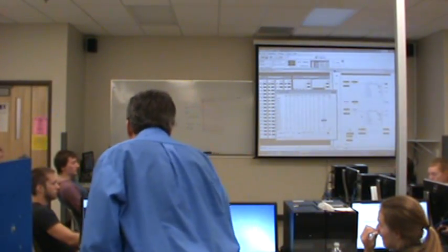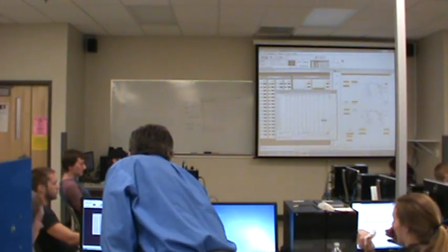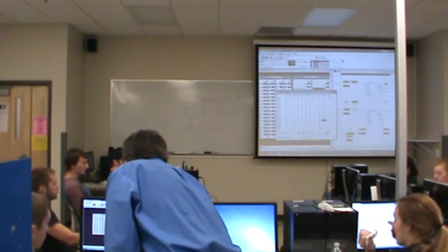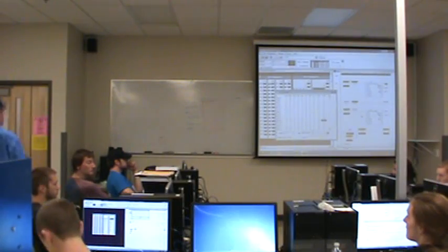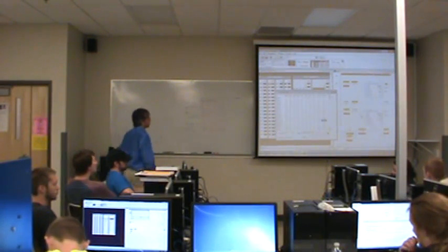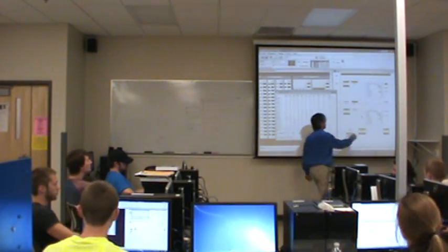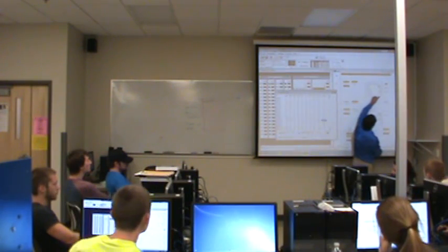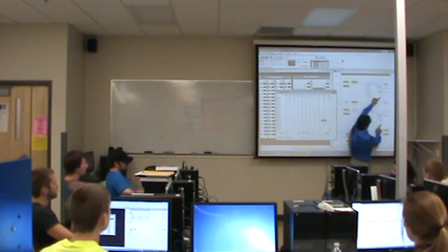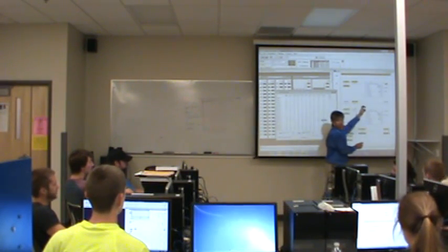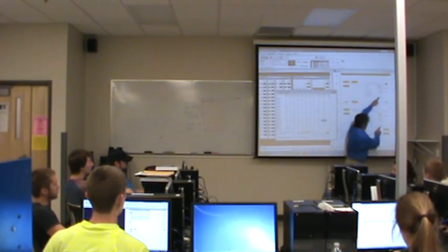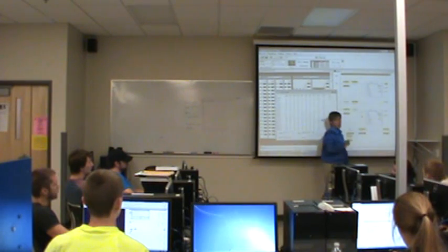Mine doesn't work either. I ran through all of them and it finally started working. Okay, well, what's happened here, let me describe this. What's happened with this sequencer, and this happens sometimes, is that the position of sequence compare is 1 ahead of sequence output. If these two get out of phase, which can happen, he's got a 5 here and a 0 here. When that happens, it won't work.